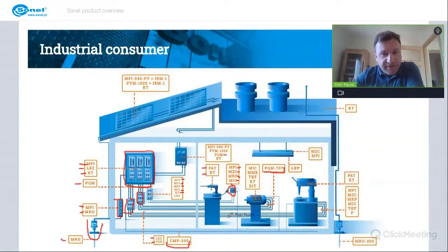Now, another device that we can find is a permanently installed device, and this is very similar. Here on the connection, we need to check short circuit loop, RCDs, insulation resistance, phase rotation, and the level of voltage. So we have all different single function meters here: MZC for short circuit loop, MRP for RCDs, MIC for insulation resistance, TKF, that's a phase rotation meter, and testers of P series, that's for voltage.